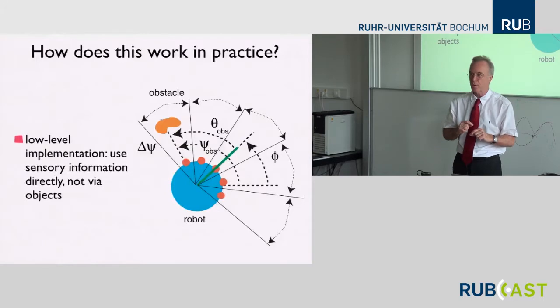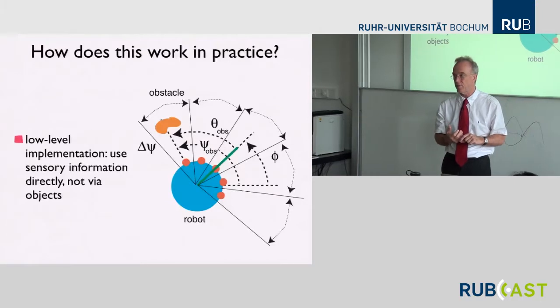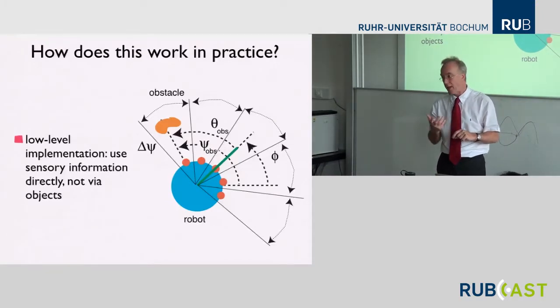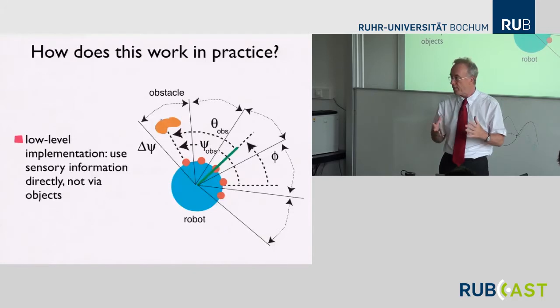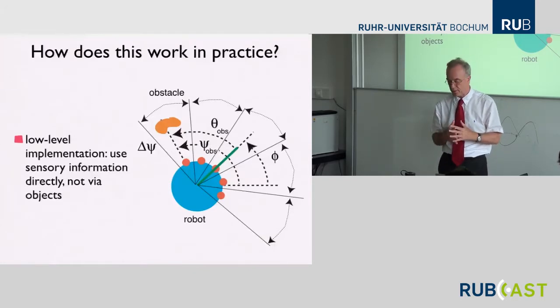It sends an infrared beam out into a direction, and it measures the infrared light that comes back. And if there's a surface close, more will come back than if there's a surface far. It's not very calibrated. If the surface is large, you will get more signal than if it's not large. If it's white, you get more signal than if it's black. So it's pretty terrible, but it already is some measure of distance.